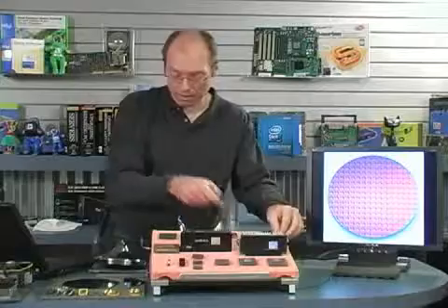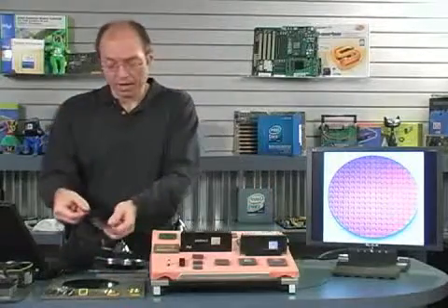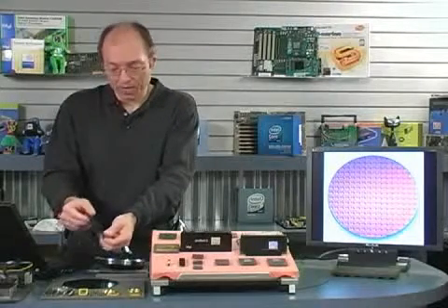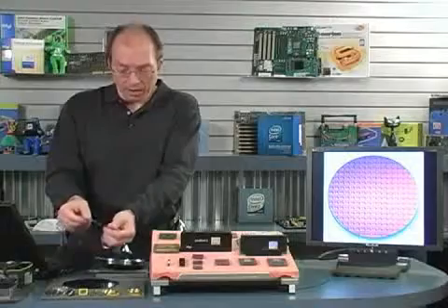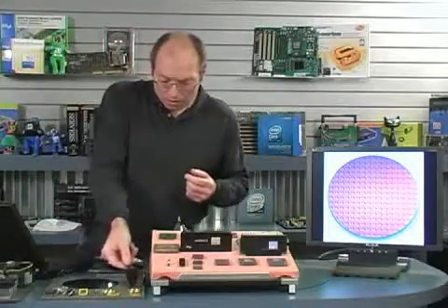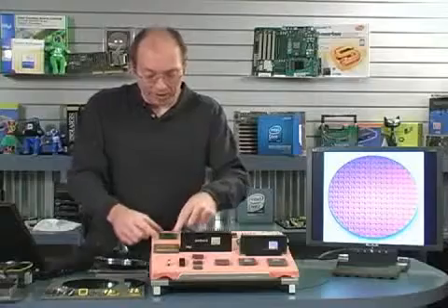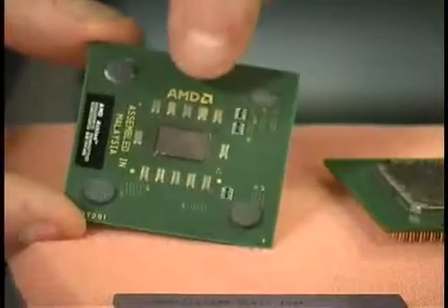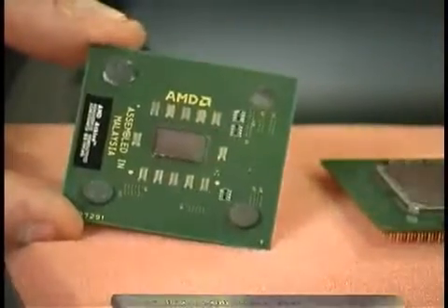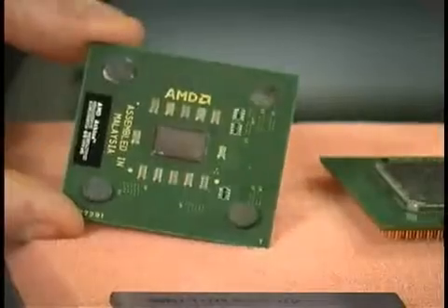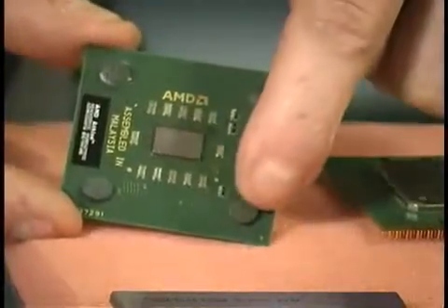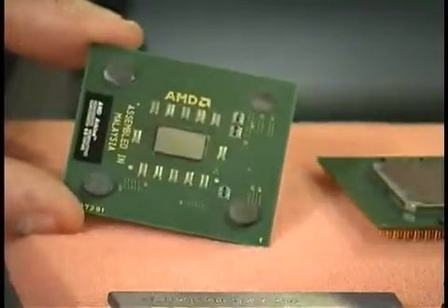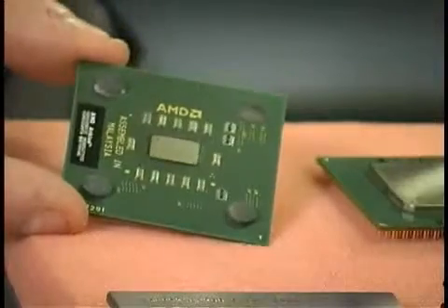Silicon is like glass. In fact, here I have a piece of a wafer that I broke earlier, and it shatters like glass, with shards flying everywhere. The edges are extremely sharp. It's very brittle. So what would happen was when you put a heatsink on a chip like that, and here's an example from AMD, this is an AMD Athlon processor with the raw processor die sitting right in the middle of the chip, if you put pressure on it, it would crack the die. What AMD did was put rubber pads around each of the 4 corners to try to mitigate that problem, but still it was happening all too frequently.